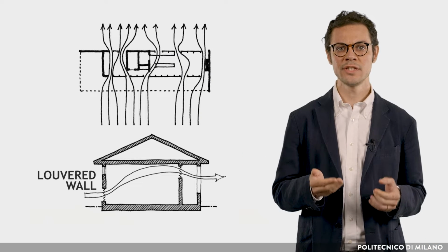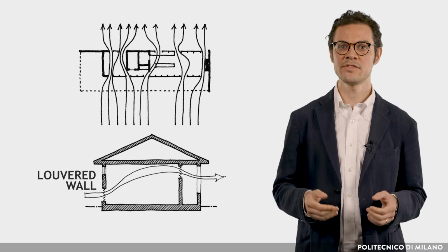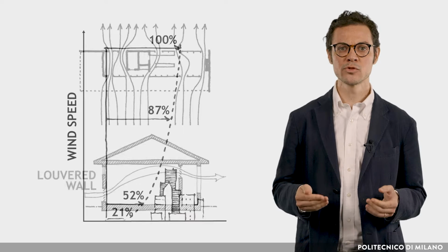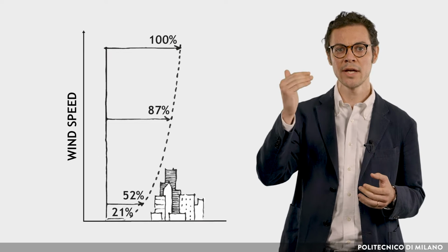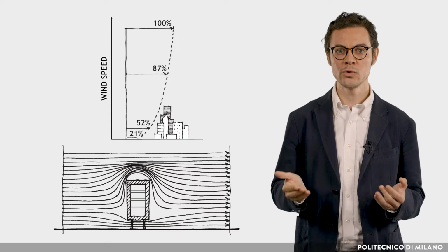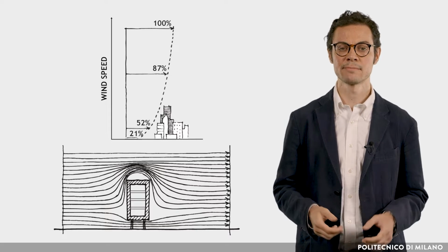Cross ventilation, in this sense, represents a very effective solution. In order to enhance ventilation, buildings should be more than 1 story high, preferably with the ground floor left open or used for non-living purposes. And now some suggestions regarding specific building elements.